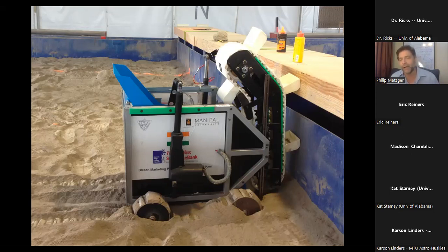Here's another little trick to remember. The maximum traction that you can get on your vehicle is not a function of the vehicle. It's a function of the soil, because the soil is going to shear, and whatever the shear stress is, that in your free body diagram is the maximum amount that can transmit from the boundary to your vehicle. And so it's a function of the soil properties. And if the amount of traction is not enough to lift your vehicle out of a hole, then you're not getting out of that hole. So you want to avoid it starting in the first place.